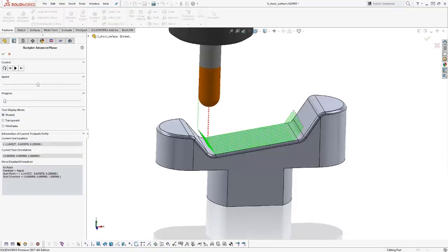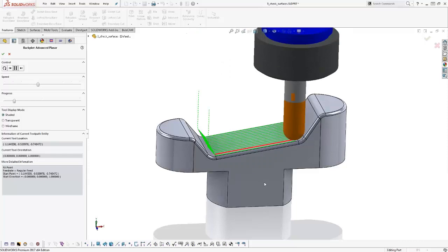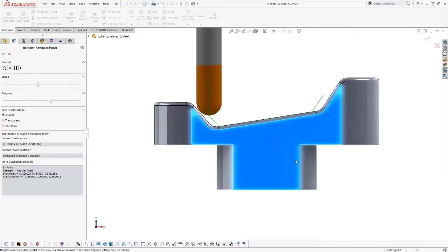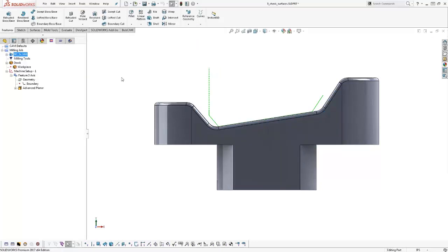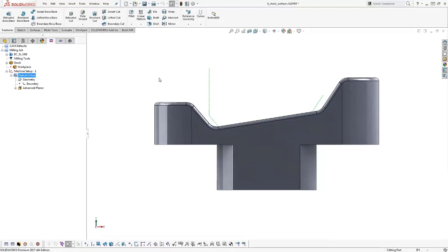So there's a lot of different ways. I don't know if this is the best example to show this, but there are a lot of different ways in which this could be beneficial for you to drive your tool in an area, and instead of trimming away, just leaving additional stock or driving the tool up, okay? So this is using tool retract in this particular example. All right, now let's go into the next one here, which is, let's see, what do we got?